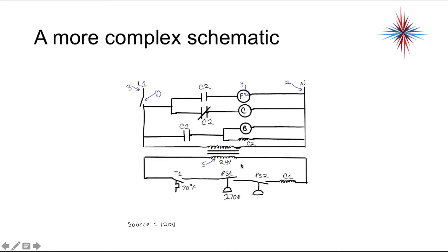Well, there's a control component someplace in here. Right there, there's a coil also labeled C2. So all the labels that are the same affect each other, just like C1 here is affected or controlled by C1 there. So when you look at a schematic, you sometimes have to look at where the other portions of the component are. And this is a schematic we will come back to.